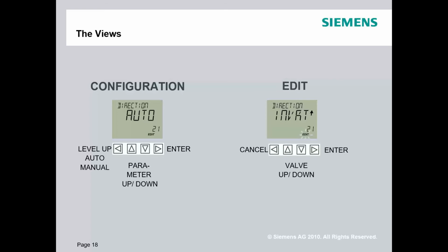Well, if I've got an actuator that can only take 40 pounds and I don't have a regulator, and I've got 100 pounds or 80 pounds of instrument air pressure, it's going to keep loading. The best thing that can happen is I blow the diaphragm out of it. The worst thing that can happen, I turn it to shrapnel. So you need to look at the actuator.